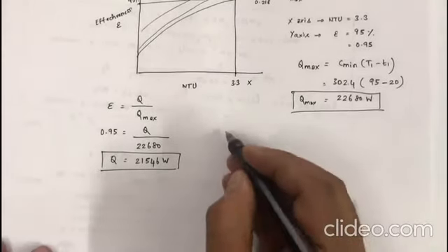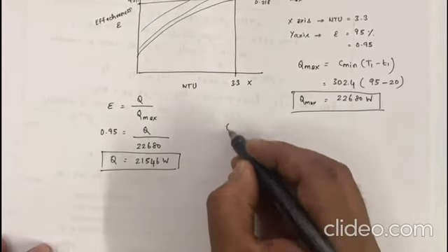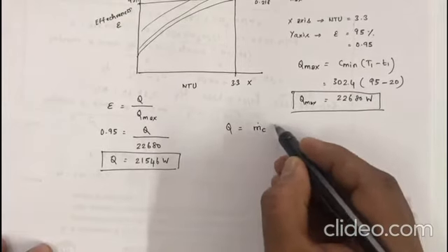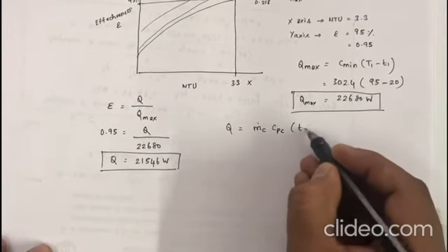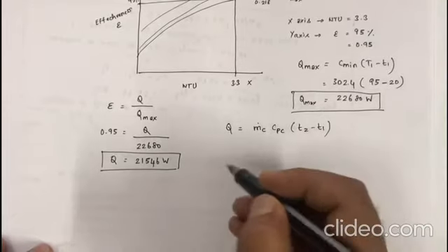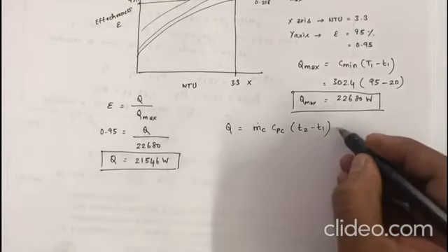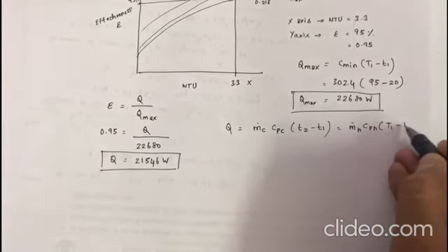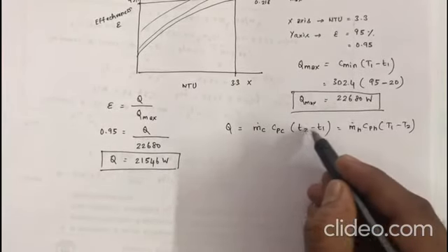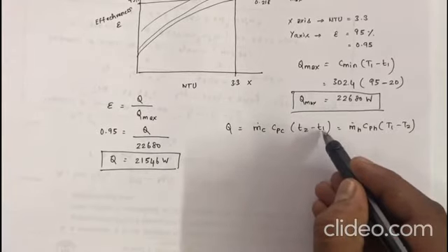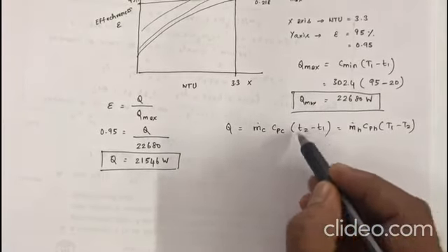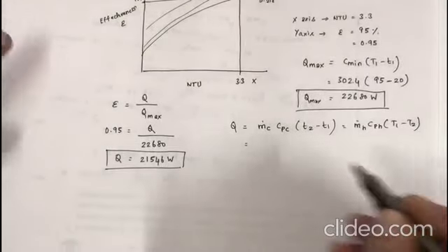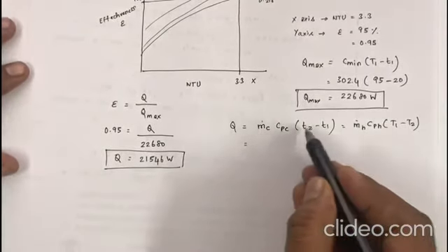Okay. So now total heat transfer is given as m c cpc into T2 minus T1. This is your familiar equation which you already know. This is also equal to m h cph into T1 minus T2. So remember, this is always large temperature minus small temperature. Remember that. Okay. So now we have a large value minus smaller value.